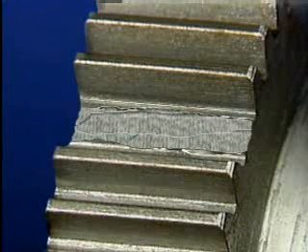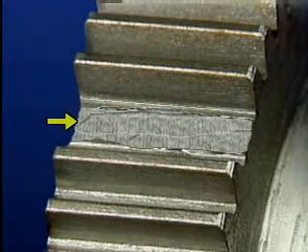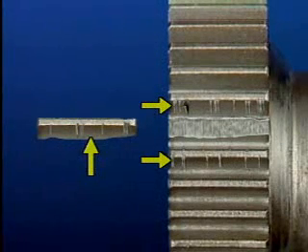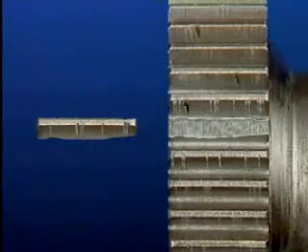Now, even if the gear teeth haven't broken, you can tell when fretting corrosion is occurring by looking for this reddish-colored stain which seeps out of the defect in the gear teeth. A defect might be so small that it can't be seen with the naked eye. However, the reddish stain will usually be visible. The appearance of a break that has been caused by overload can be described as being rough. In addition, the gear tooth broken by overloading and the adjoining gear teeth may be deformed or damaged, and in some cases of overloading, all of the teeth on a gear may be deformed or damaged.